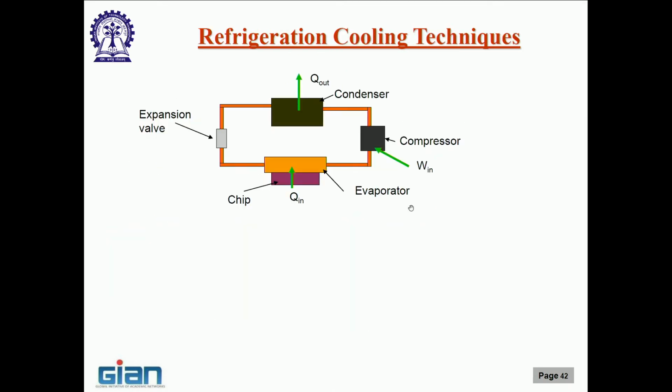So, refrigeration has also been used, and I am going to show an example later, but again that does not come for free. Of course, nothing comes for free, all these components cost money, but it does not come for free even in terms of energy, because what you finally reject is actually more than what you have extracted. Q out in an ideal system with no loss will be Q in plus the work at the compressor inlet, first law of thermodynamics, right.